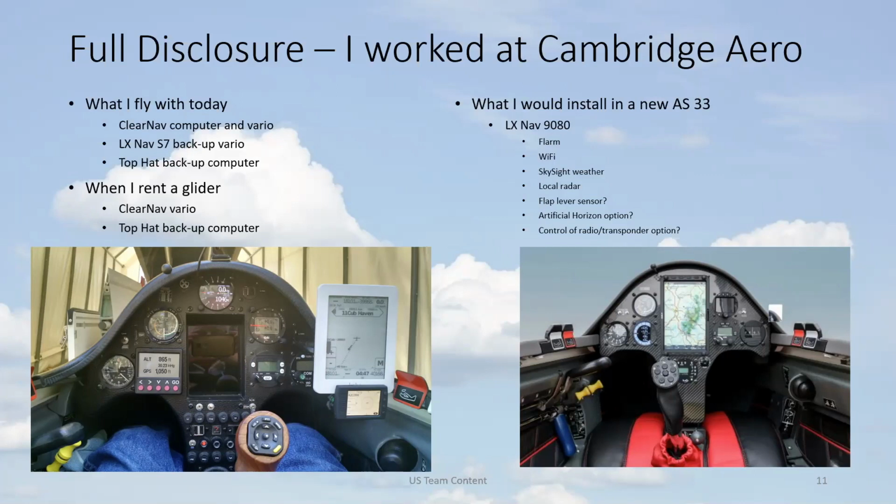No, the fuses don't help, Bob, because the batteries are trying to feed each other, and the currents that can get you to a fire are not beyond the normal discharge currents of the batteries, so the fuses would not protect against that. That's why they put Schottkys in, that was mentioned earlier. The problem is it'll likely be fine, and short exposures are likely to be fine. The problem is that the downside is really, really bad.